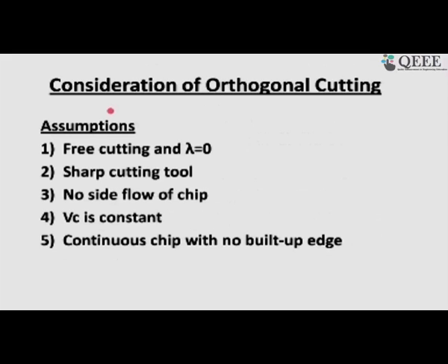Now friends, in cutting force analysis, theoretical prediction is very important and relevant, and in that case we have to make a model of the whole process. Now to simplify the process, we consider it as orthogonal cutting. Yesterday also I mentioned that orthogonal cutting is a two-dimensional phenomenon, the chip flows in the orthogonal direction, and to have that condition, the necessary condition is that lambda should be 0.